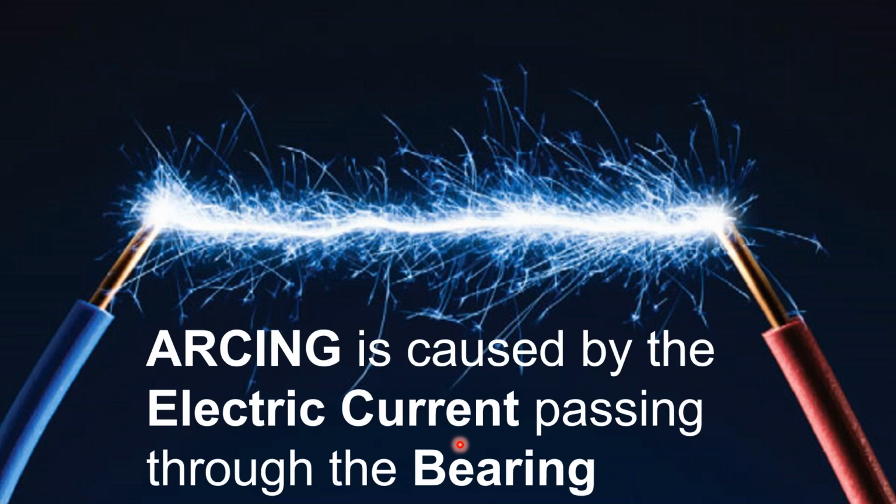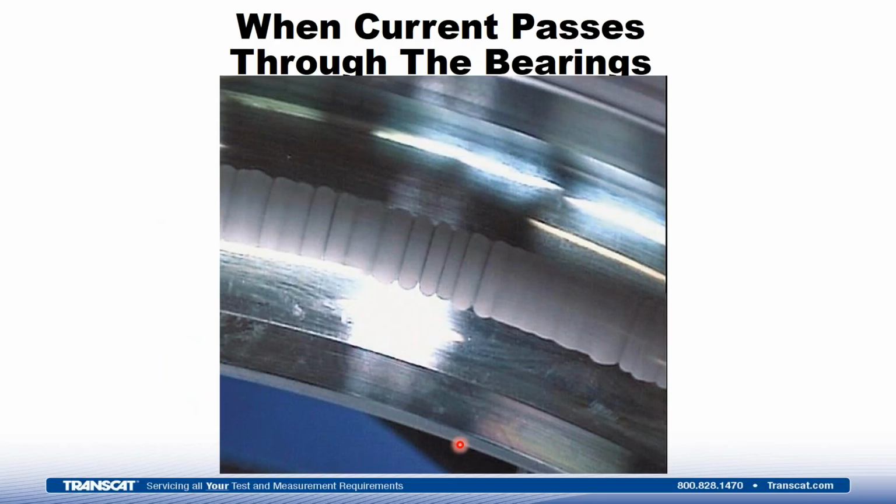So when current passes through the bearing, it creates arcing. And this arcing creates pitting or fluting in the raceway. So one of the things to do when troubleshooting a motor is to look for pitting or fluting, as seen here in this picture. Pitting would be more like little dings, and this is fluting. There shouldn't be any voltage on the shaft, but if there is, the discharge between that bearing and the race causes this pitting and this fluting effect.